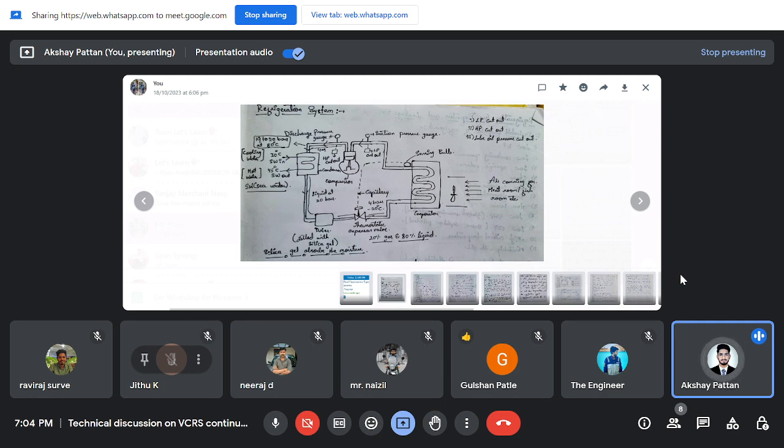Actually, low pressures occur when the cooling effect has completely taken place or when the desired temperature is achieved. Say you want minus 18 to minus 20 degrees Celsius at the fish room or freezer compartment, and that temperature is already achieved there. Then there is no meaning in running the cycle again, with the flow of refrigerant continuously taking place.